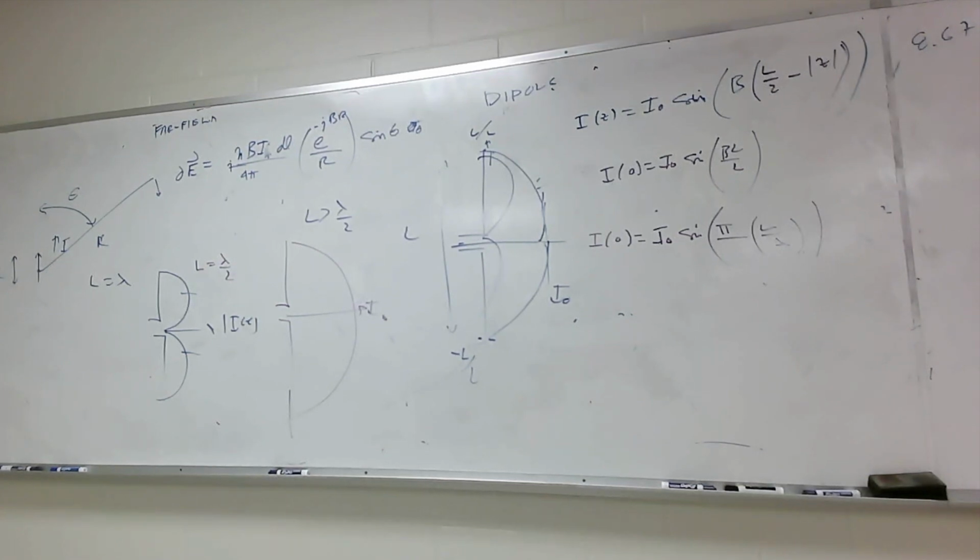But what we're doing is all straight wire antennas. Short dipoles are going to have a given impedance that we know, right? We know the power density, we know everything about the fields. Arbitrarily long dipole antennas are generally interesting to know about in terms of the field formulations. But the most important one is the half-wave dipole. That's the one everybody uses. The impedance of that is about 73.2 ohms plus j42.5, but it is a function of the radius.